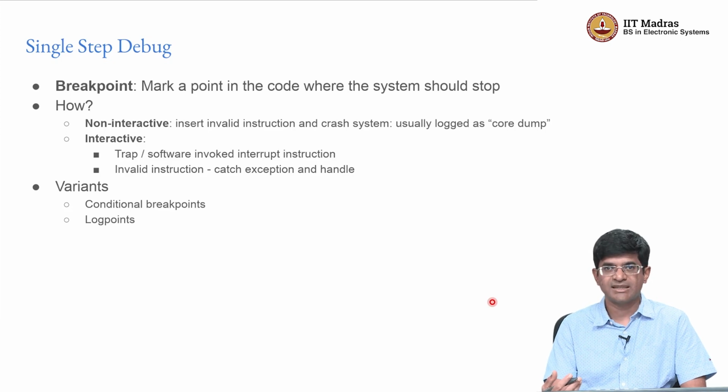The amount of information you can transmit through LEDs is minimal. Even through printf statements is not very great, for the simple reason that adding too many printf statements will dramatically increase the size of your code. More importantly, it can also give rise to certain kinds of bugs that occur only in the absence of the printf statements. How does that happen? As we have discussed earlier, printf statements tend to be slow. They change the timing with which certain operations are performed, and therefore having an exact reproduction of the runtime scenario under the conditions of a printf statement may not always be possible.